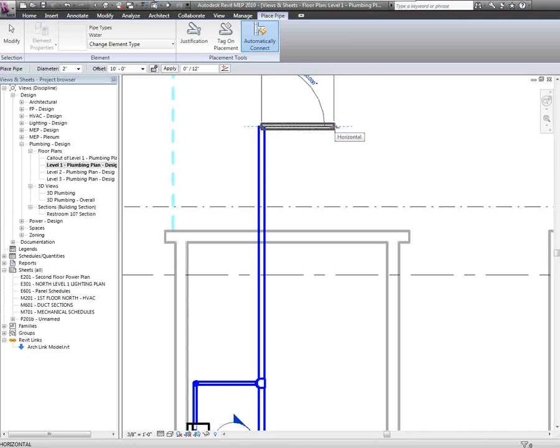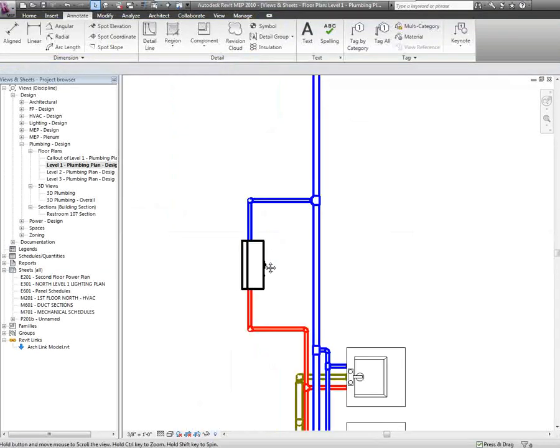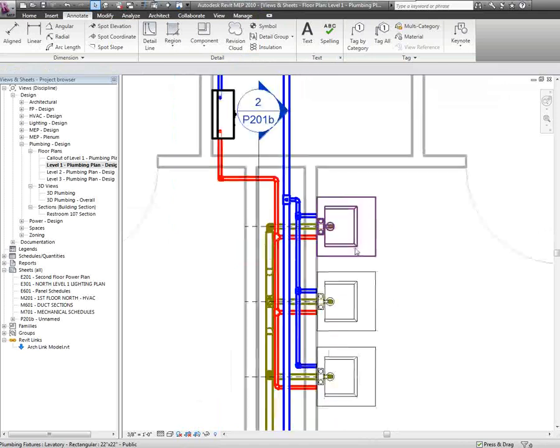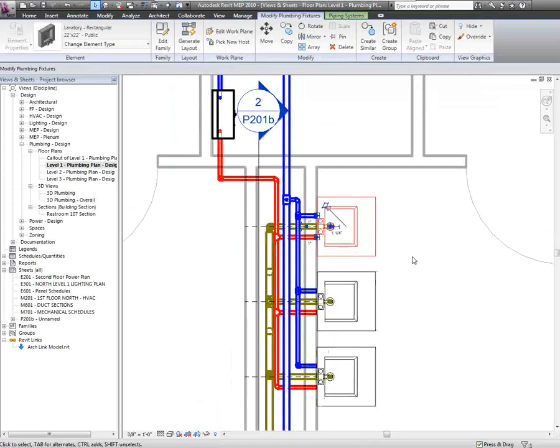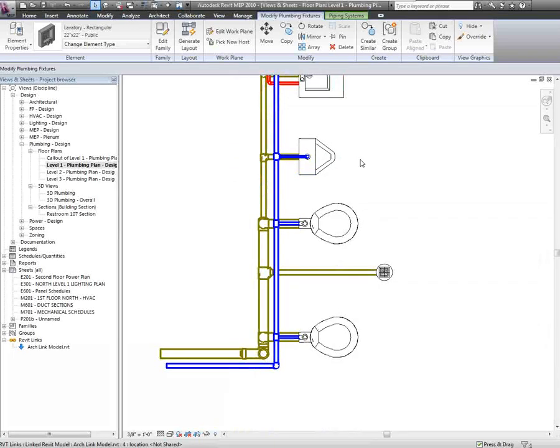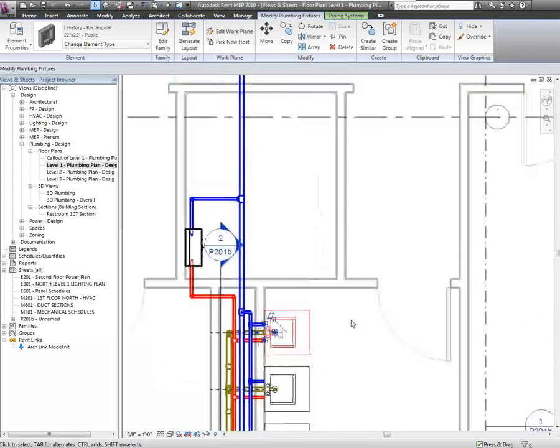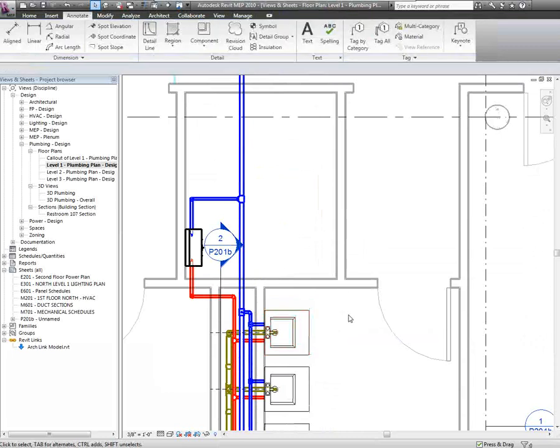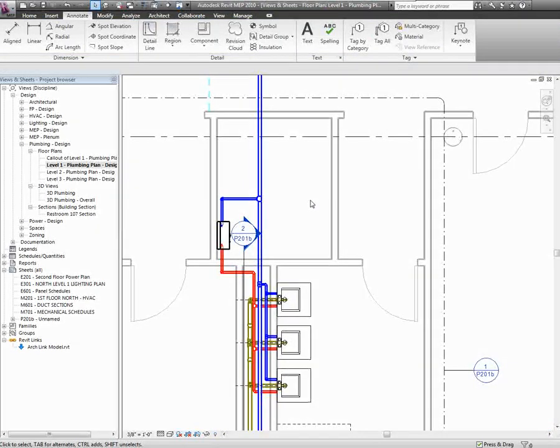You're very welcome. And the space bar works the same for equipment. If I want to flip equipment around, like this sink right here, I'm probably going to mess things up. Actually that sink is a bad example, but any type of equipment that's not attached to a wall will rotate for us. And the tags of course rotate as well if you hit the space bar after selecting it.